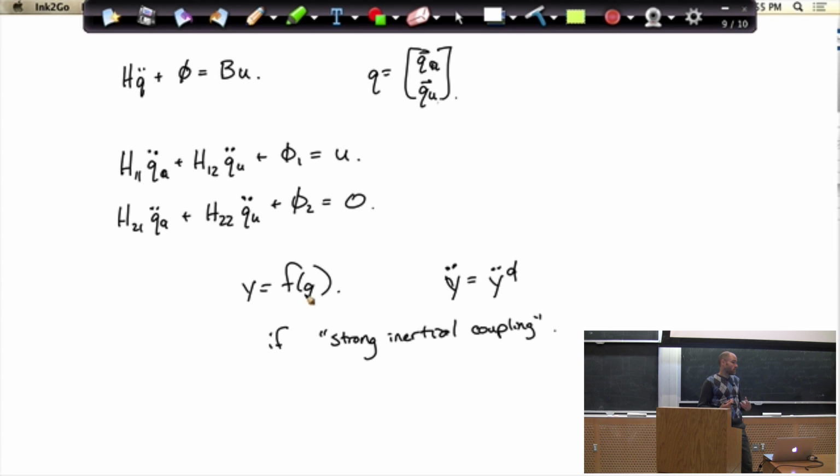But it turns out this notion of partial feedback linearization is very general for the manipulator equations. In general, if you have n motors, or m motors, let's say, I normally use m for the motors, then I can roughly control m quantities of my system with partial feedback linearization. The times it's not going to work is that, let's say I have a motor attached to this desk, and I want to command something way over there, and they're just not attached at all. That's not going to work, right?